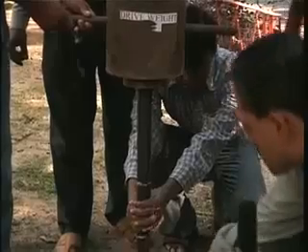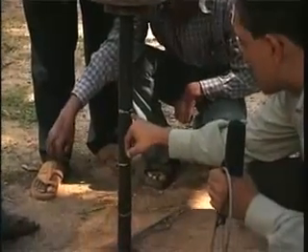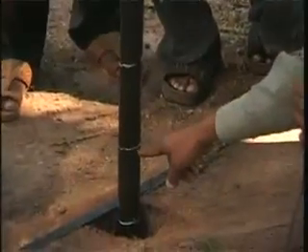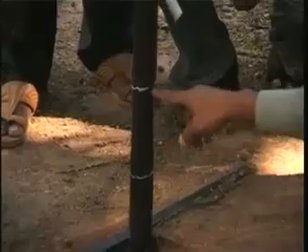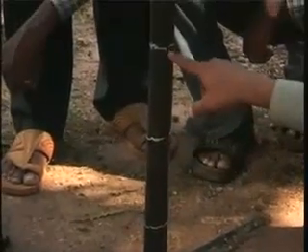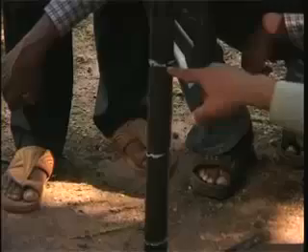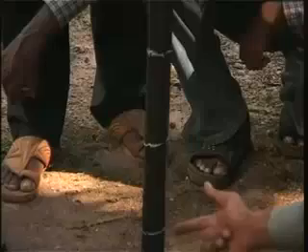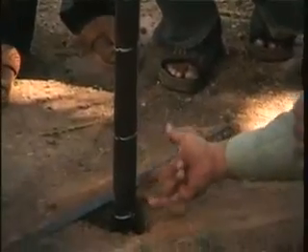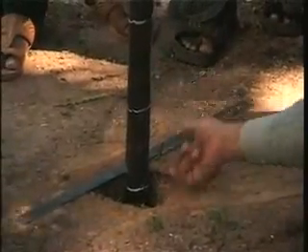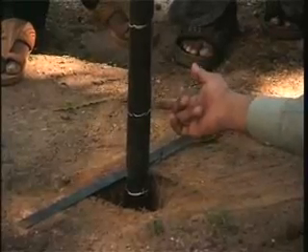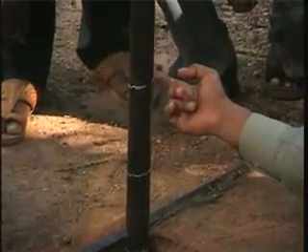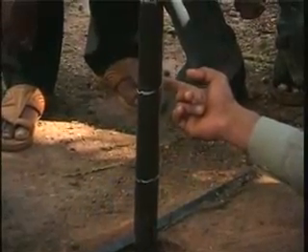What you also see is that we have three markings at 150 millimeter spacing: one at the top of the hole, then one 150 millimeter above, the next one 300 millimeter above, and the third one at 450 millimeter above the top of the hole. So we are going to measure the number of blows required for the penetration of this length from here to here, then from here to here, and finally from here to here.